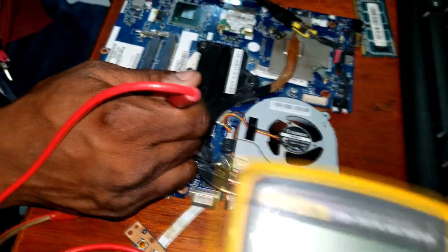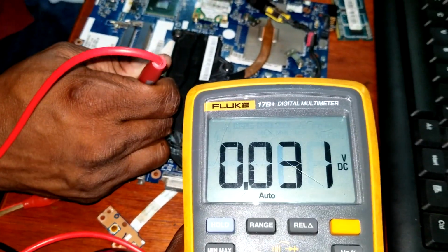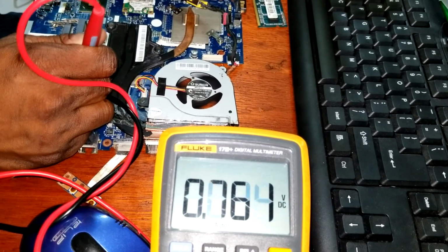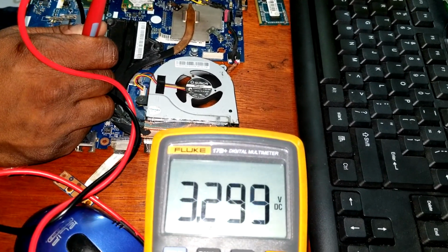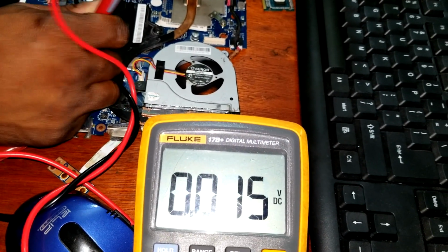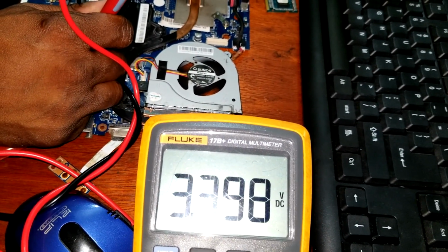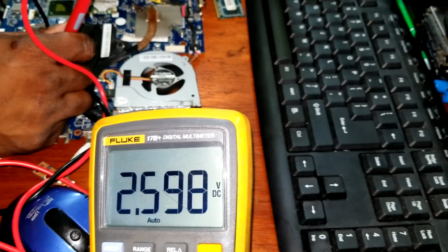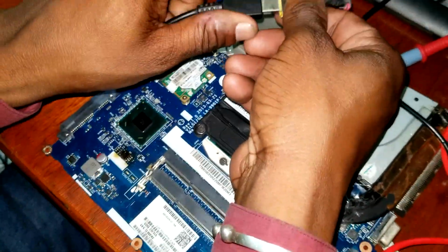If we turn them on, these should give us 3.3 volts, which is pulled up all the time. So let's measure that. Let's turn on. Pin 200, 3.3 volts is there. Pin 202, 3.3 volts. So these are the clock and data signals, right? Clock and data, 200 and 202. We're going to check those two signals with the oscilloscope.